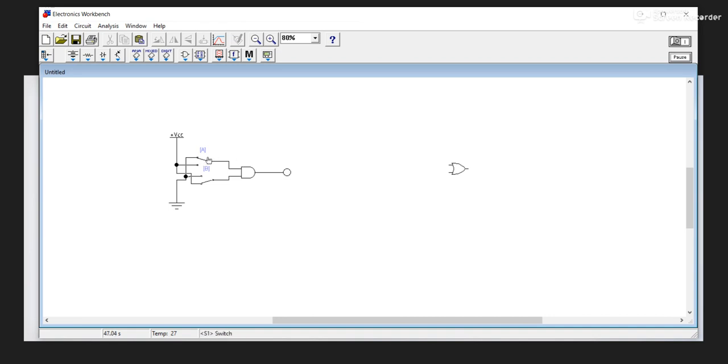Now if I now switch A back, you will notice that there is an output here. What we have here is 1 and 1 at this point in time. Now that is the simple operation of an AND gate. Now if I quickly turn this off, rather let me just delete the connection here. This connection here, I've deleted it.